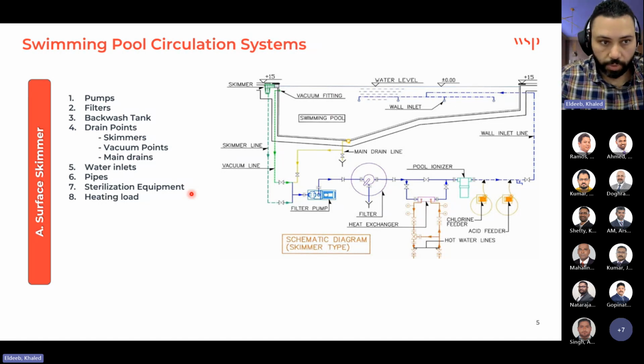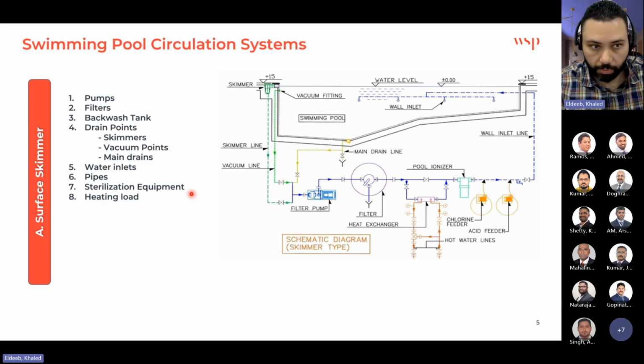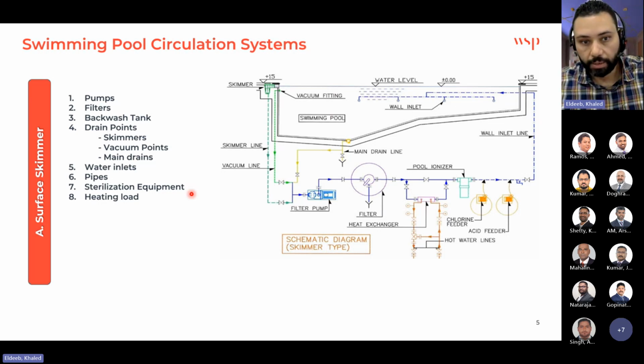So to resolve it, because we cannot connect pressurized drain to our current drain system, in order to resolve this issue, we invented something called the backwash tank, to slow down the chamber to accommodate the high pressure volume coming from the backwash when we clean the filter, to make it the same like gravity drain or gravity drain to accommodate this one in our network as a WSCB.